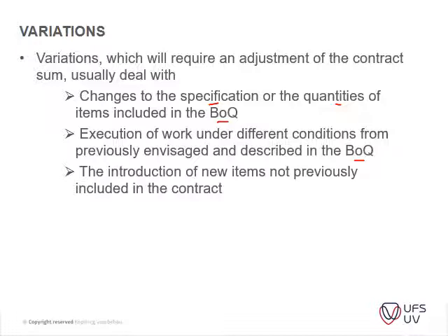Whereas if it's changed, for instance, from a non-compliant swimming pool at the start of the project to a FINA compliant swimming pool, where the tolerances are much stricter, it will constitute additional cost because the contractor has to spend more time in getting the accuracy correct. So I hope that explained it better for you. Another thing might be just getting the strength of the concrete stronger also.